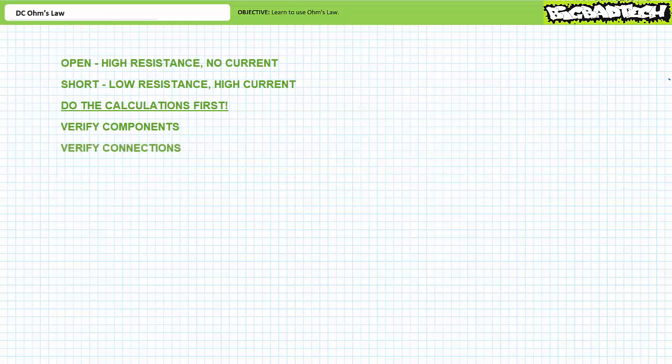Double check the circuit. Make sure it's hooked up as intended. Use colored wires and label the nodes. Look at anything you suspect of being open from all angles, not just the top. Different viewpoints often quickly reveal a missed or off by one connection.